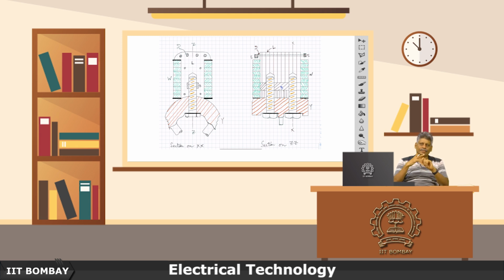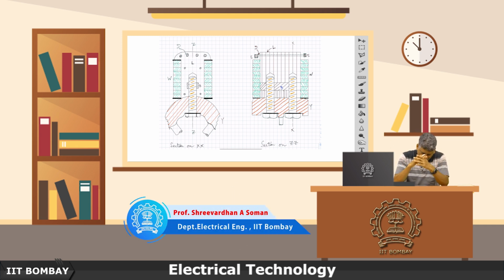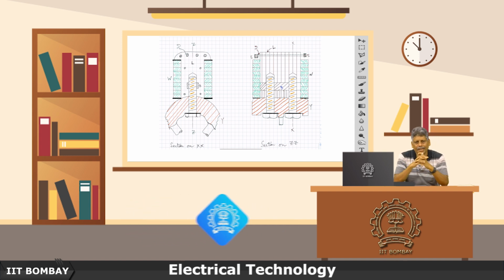What is a mechanical radian, what is an electrical radian? Electrical radian means once you have multiplied it by a factor of p by 2 and converted it into the electrical side signal, then the angles there are called electrical radians, and the angles on the mechanical side before that multiplier effect happened, the physical geometry, those are the mechanical radians. Electrical radians are again p by 2 times the mechanical radians, just as the electrical frequency is p by 2 times the mechanical frequency. So, I think we will take a break here, and in the next class we will start with the stator windings.